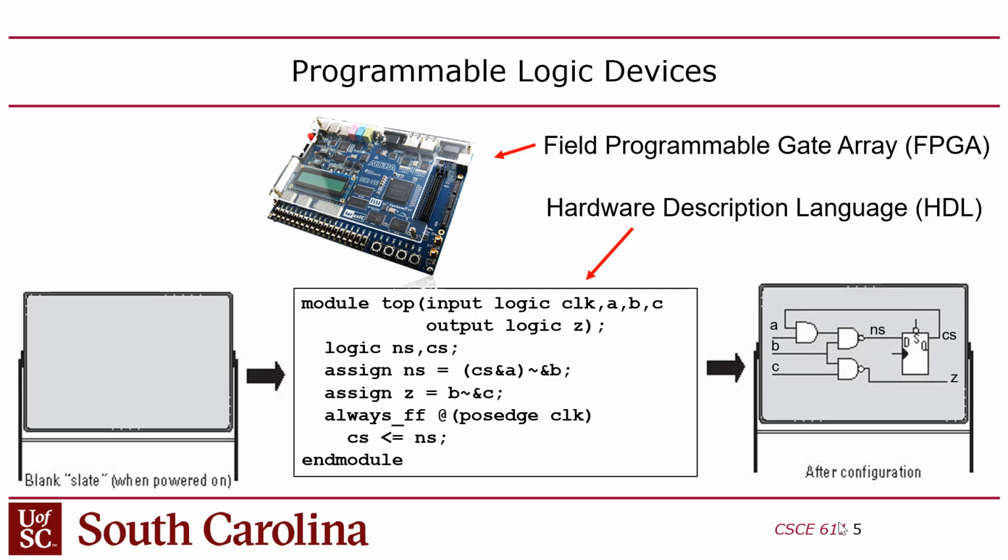And the way that works is the FPGA is a two-dimensional grid of lookup tables, each of which can be initialized in a way where they can become an arbitrary logic gate. And those lookup tables on this FPGA, I think, have 6 inputs and 1 output. So this FPGA has 115,000 6-input lookup tables that each can be a gate. So essentially there's 115,000 gates. That's the capacity of the chip.